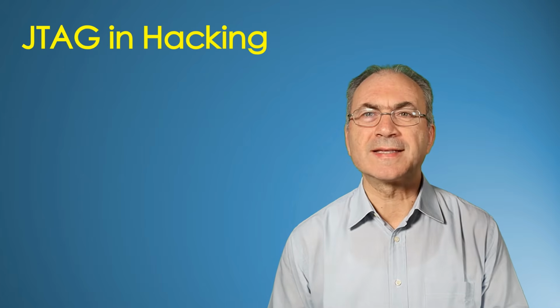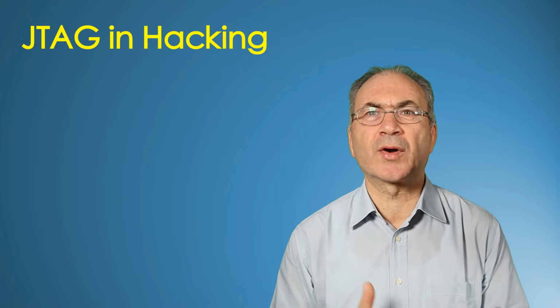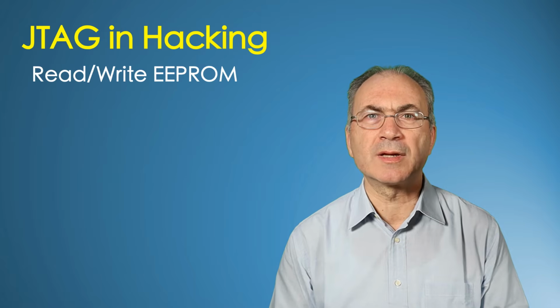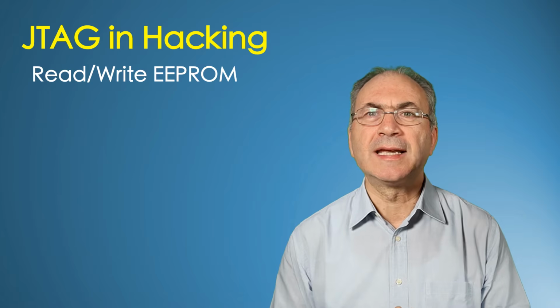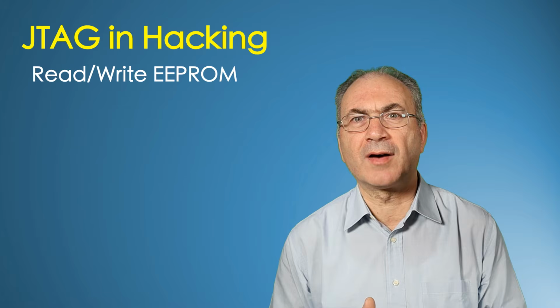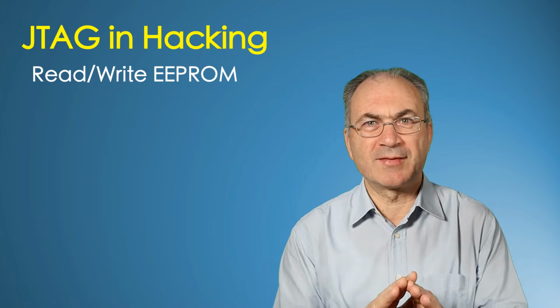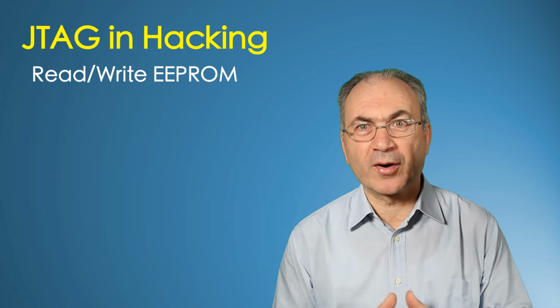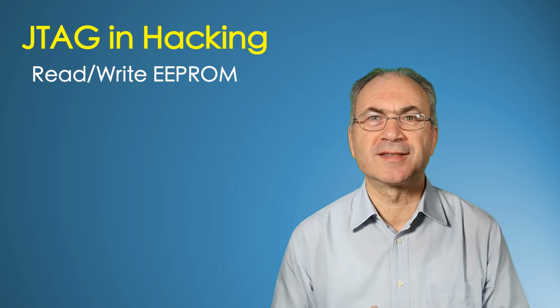In hardware hacking projects, we are very interested in the JTAG interface, mainly for 2 reasons. The first reason is that it allows us to read and write the content of the EPROM, so it can be used to dump the entire EPROM content. It can also be used to restore the original firmware in case of breaking the device during our firmware modification trials. Obviously, we should have saved the original firmware before tinkering with it, but every one of us does this.